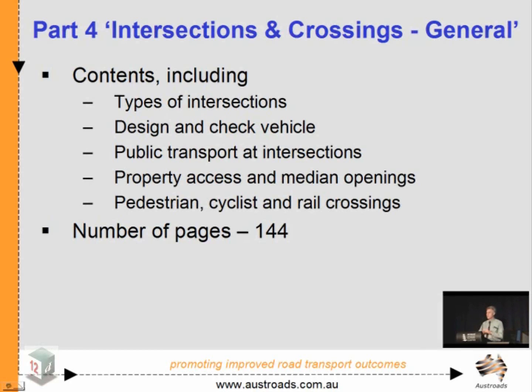Leah's asked there, one of the other issues with definitions is how we define vertical curves. For a vertical crest curve, typically in Queensland we've always used an R value of radius. It was decided at the Austroads level that it was only Queensland that did that, and there were one or two other states that went a bit both ways in which definition they used. It was decided that they will go to K values. Now, K value is just the radius divided by 100.